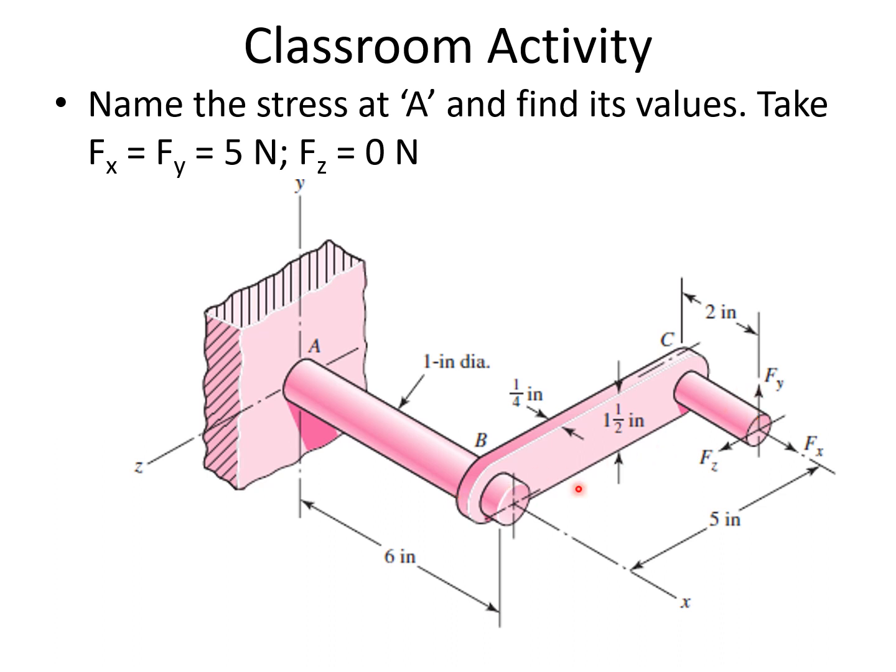Due to this eccentricity, this rod may bend like this. So because of this bending moment at A, you may experience a bending stress also.